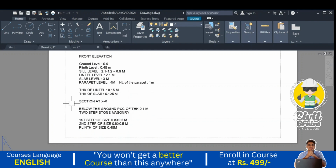Okay, so here in this section, below the ground level, PCC of 0.1 meter we just take. Next two steps of stone masonry. The first step is 0.8 by 0.5 meter, that is 0.8 is the width and 0.5 is the depth, and the second step is 0.6 width and 0.5 depth, and the third one is the plinth, size 0.45 meter. Depth depends upon this one. So now I just go to the AutoCAD.